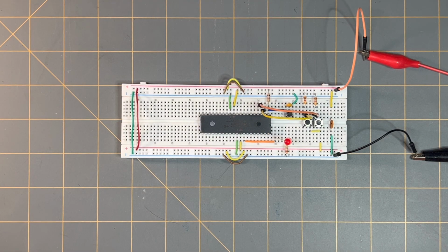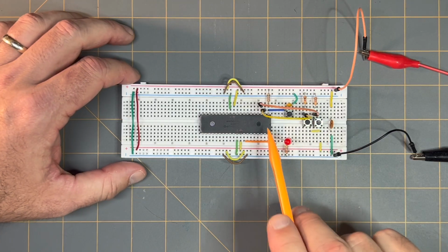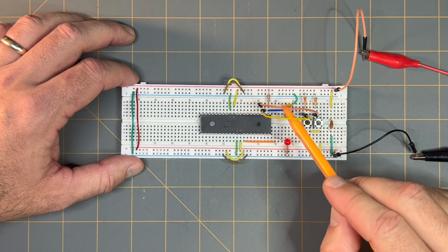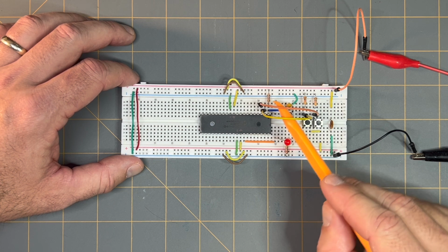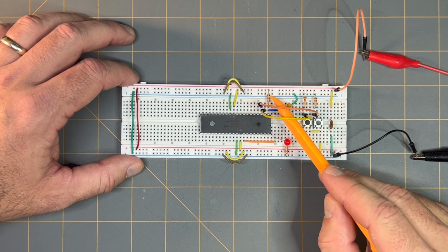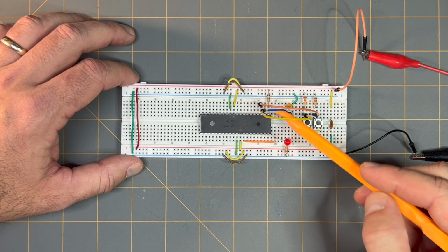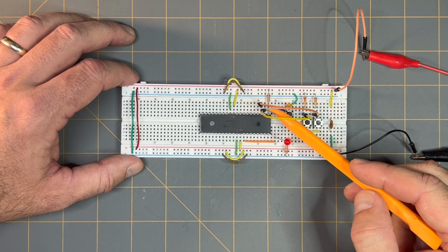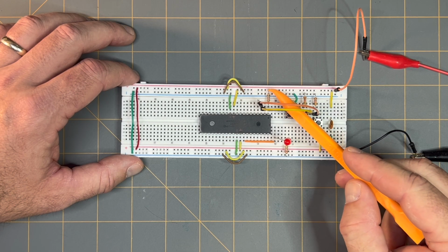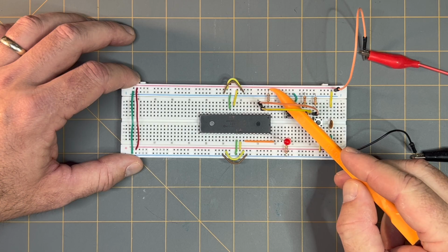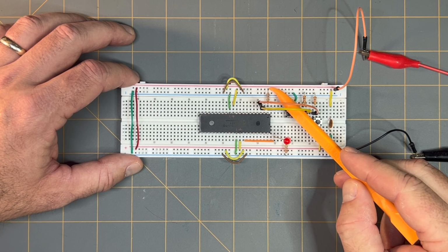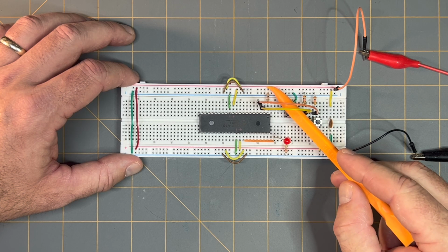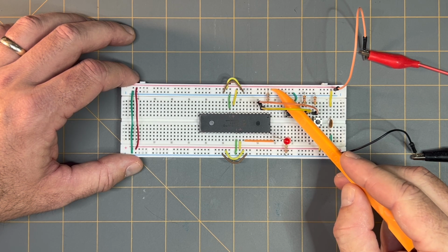To make the MCLR connection for the reset button for the PIC microcontroller, I took a 1 kilo ohm resistor and placed, I don't know if you can see it, but it's this resistor here, and placed one of its leads in line with pin 1 of the PIC microcontroller in point B22 on the breadboard. I placed the opposite lead of that 1 kilo ohm resistor into one of the neighboring positive power supply points on the breadboard, or the positive power rail.